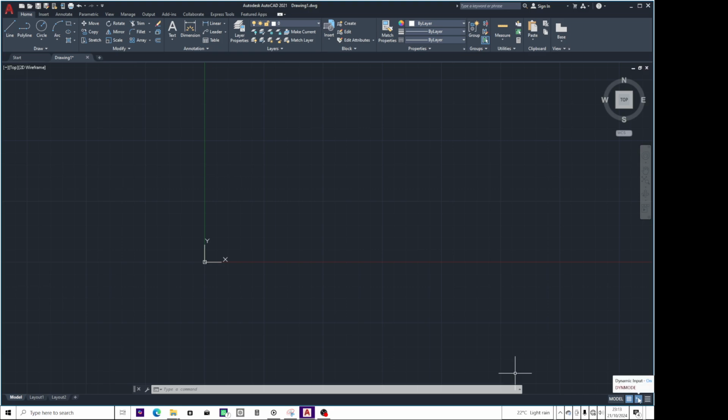The use of that dynamic input is that you are able to visualize or view whatever commands you want to input into your application. For example, once I go in for a line and I draw, give it direction, you see the digits and the angle.